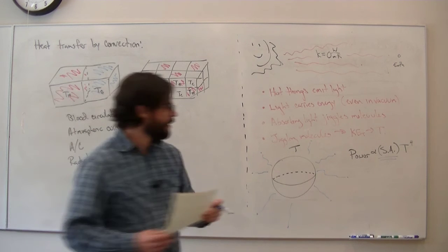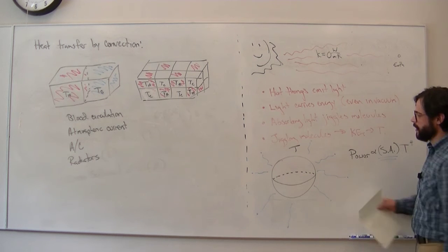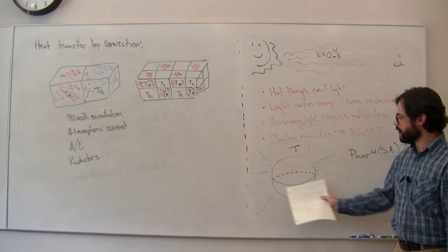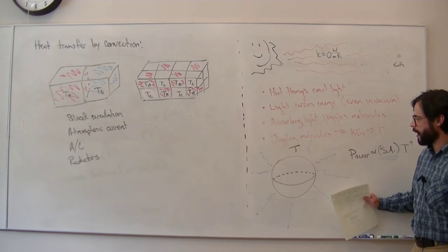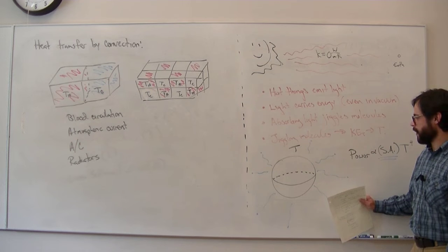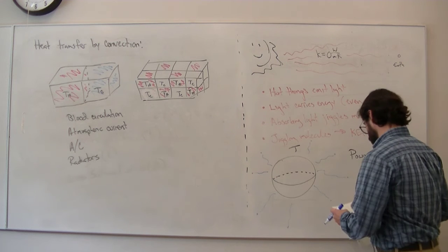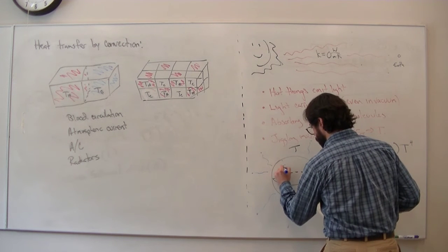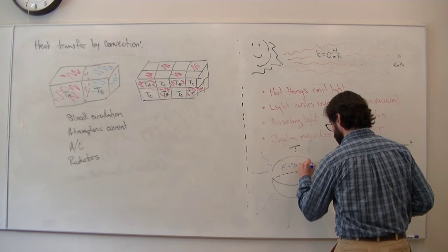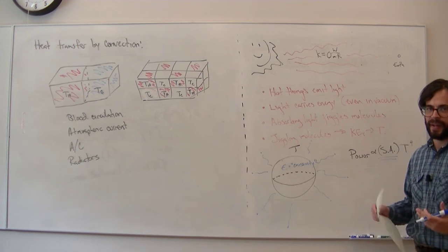So it turns out that there are a couple of other parameters. One is kind of empirical. Different things are better or worse at emitting and absorbing light. So if this was maybe like black Kevlar or something like that versus a shiny mirrored disco ball, it would actually behave a little bit differently in terms of reflecting and absorbing light. So there's a constant, it's kind of like a BS constant. It's called emissivity. And emissivity is this fudge factor that basically depends on how shiny you are.